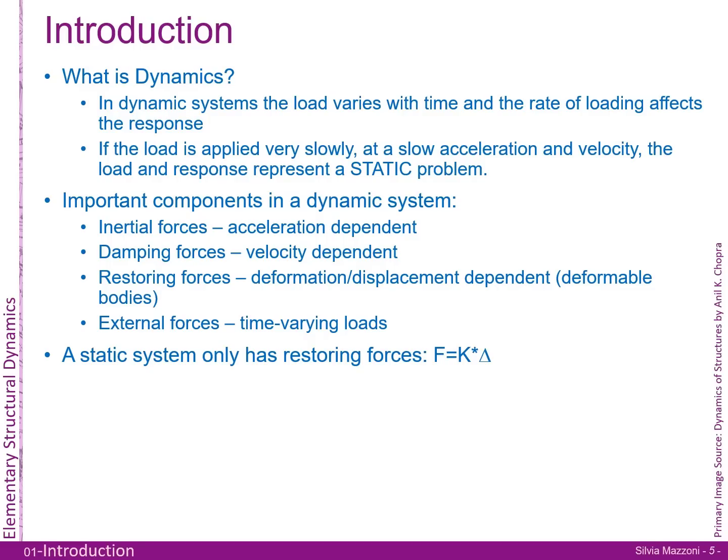But if you all of a sudden just dump a whole floor slab on top of your building, your system is actually going to oscillate and bring dynamics into the equation. So it's very important. That's really the difference: is the load a function of time, and is the response affected by this time variability? So is the rate of loading important? If it's loading really slowly, at a very slow acceleration and velocity, then the load and the response represent a static problem. And that's really what we've dealt with all this time. So what we're really bringing in is the time variable into the equation.